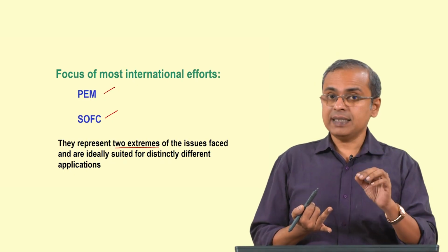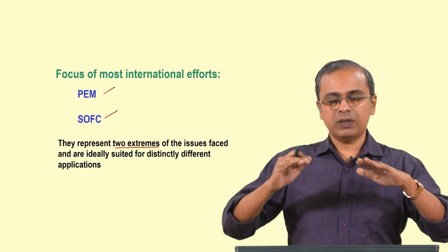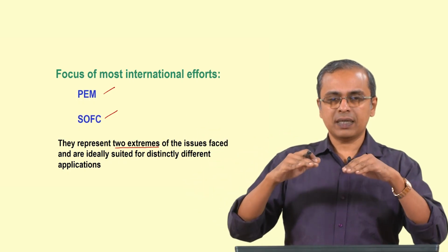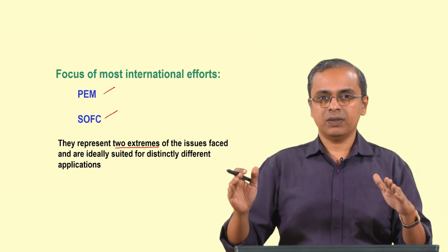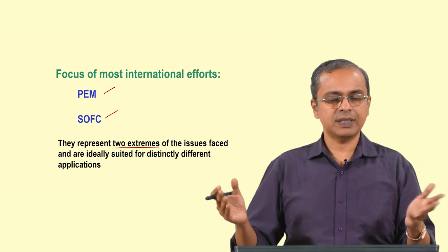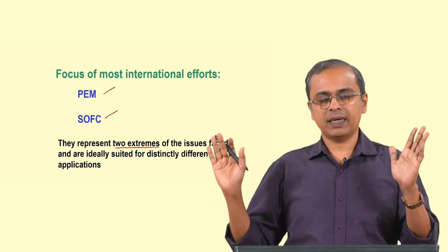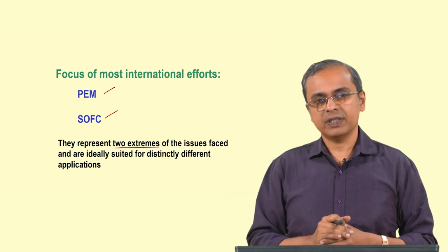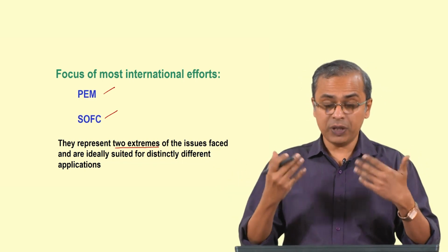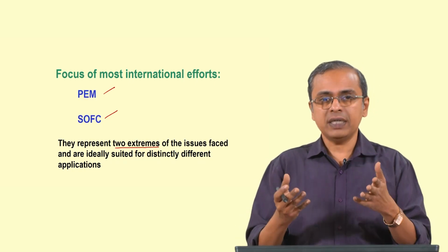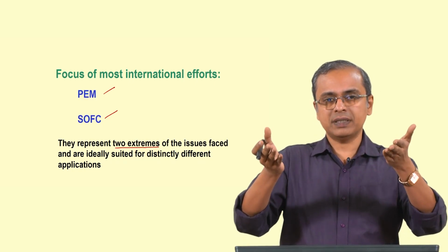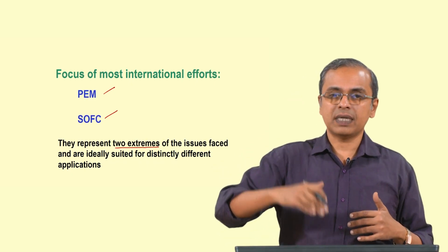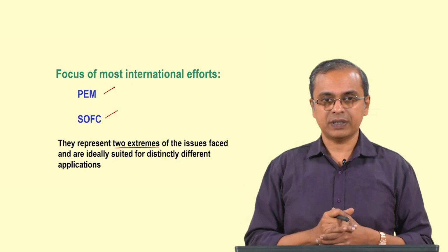Now if you look at stationary applications, the power is typically consumed on a steady basis. So the issue of startup and shutdown is not so high. You have many houses powered using a fuel cell, that fuel cell can sit operating comfortably for a long period of time. So there, having a solid oxide fuel cell works very well. At least the potential is there. It still has issues, but the potential is there because it can be set at a high temperature and can remain there. You do not have repeated startup and shutdown cycles occurring on the fuel cell.